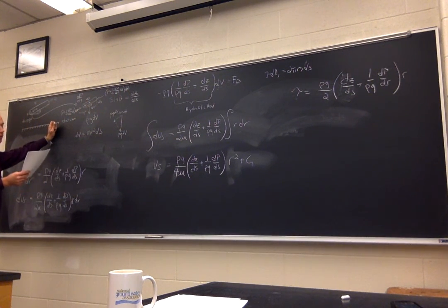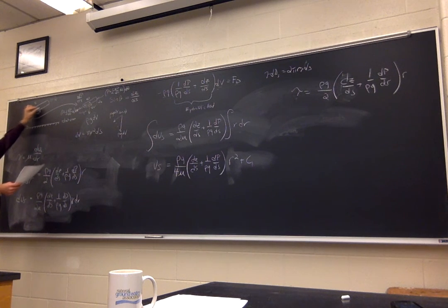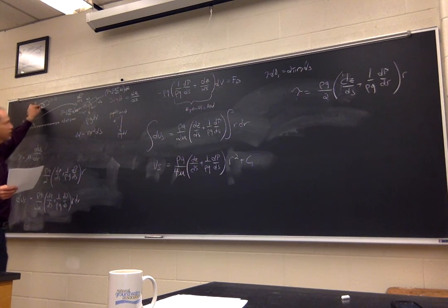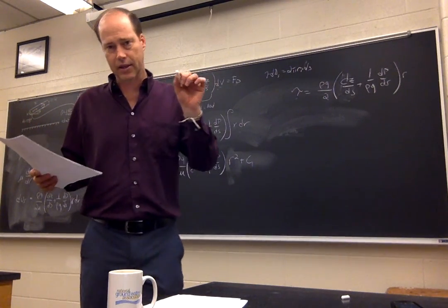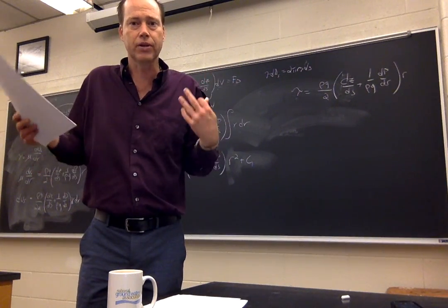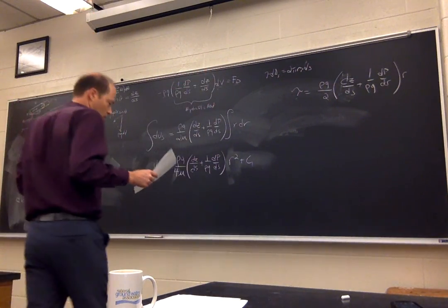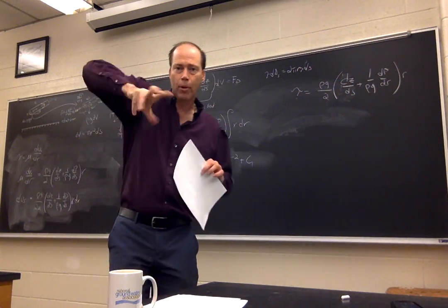So, in this problem, if I look at the velocity profile, I already kind of mentioned at the beginning that effectively what we're going to create, because we know this is the case mentally, is that the fastest velocity is going to be in the middle of the pipe. And then if we define the edges to have the frictional force, the resistive forces, if we assume that there are no slip conditions, that no slip condition means that the velocity on the edge of that pipe is equal to 0. At exactly the edge of that pipe is equal to 0. That should create a paraboloid.